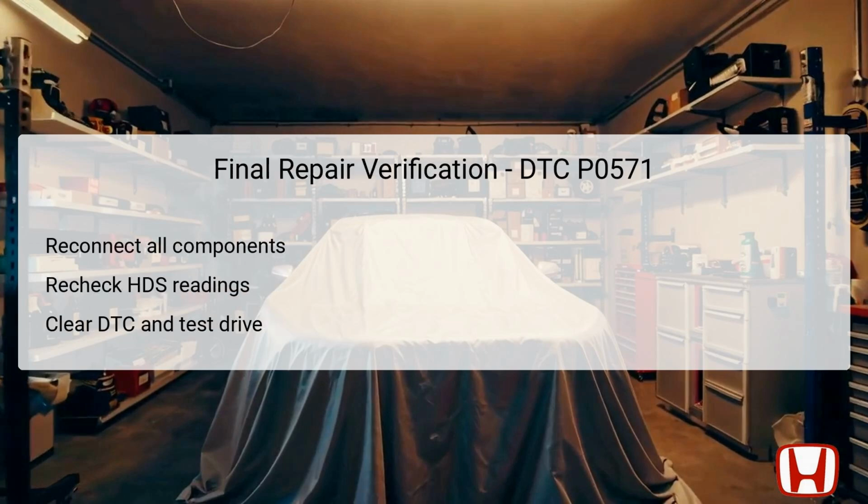After completing all prior inspections and potential repairs, it is crucial to perform a final verification. Start by reconnecting all components to their respective connectors, ensuring secure connections to avoid future issues. Once everything is reconnected, employ the HDS to recheck system readings, particularly focusing on the brake switch value. This is vital to ensure that the repairs had a correct and lasting impact on the circuit.